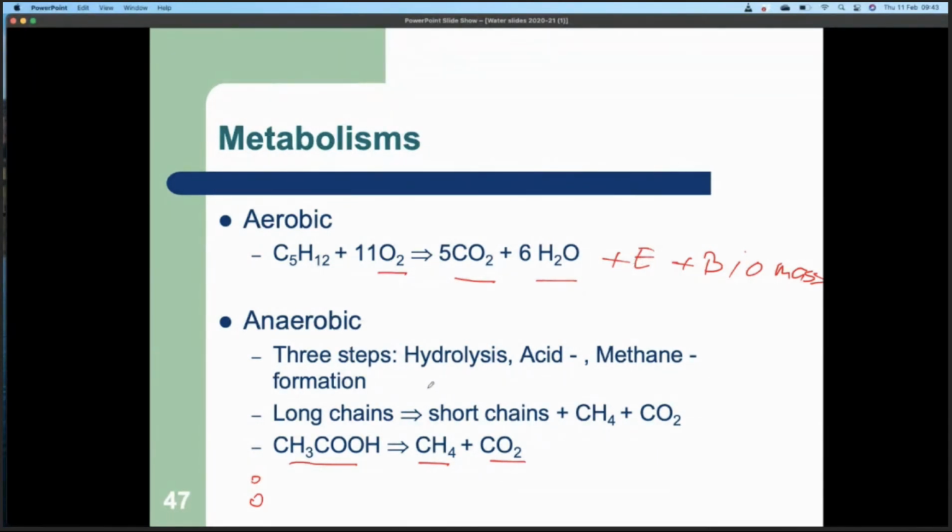So if you look at it just like this, say these are aerobic, anaerobic. Aerobic bacteria need oxygen, and we could also say they need energy, because in order to get that oxygen into the water in the sewage treatment works, you need pumps, blowers, stuff that constantly replenishes the oxygen consumption in the water, and that takes a lot of energy.